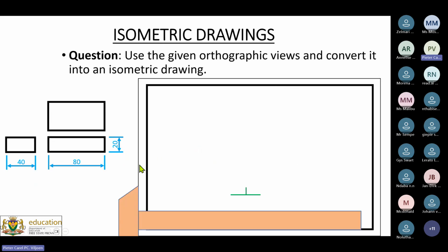All right. So how do I do this part over here? It's 20 millimeters. So you take your set square and you slide your set square on your T-square the whole time. The T-square you slide with your drawing board to the left-hand side the whole time. Okay, so it goes from there 80 millimeters.